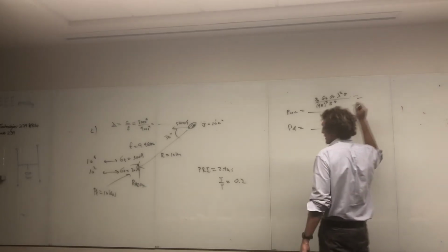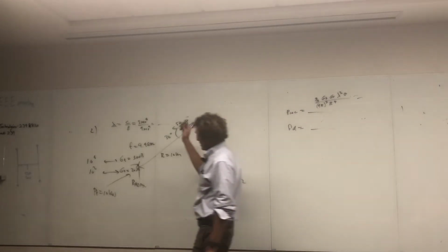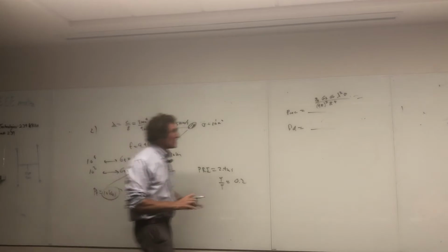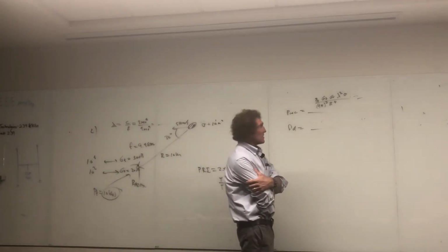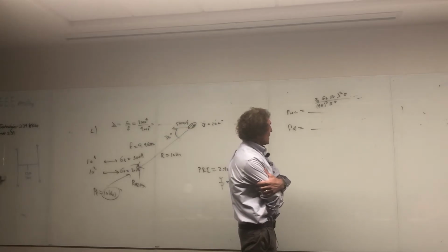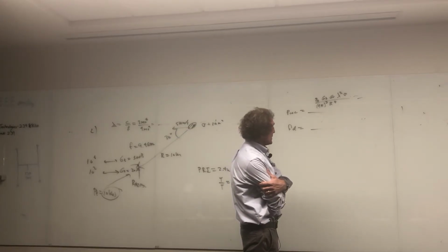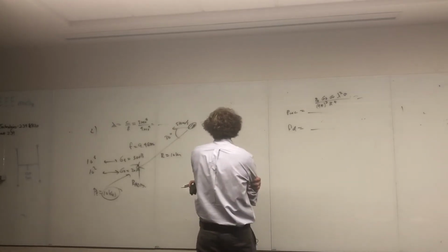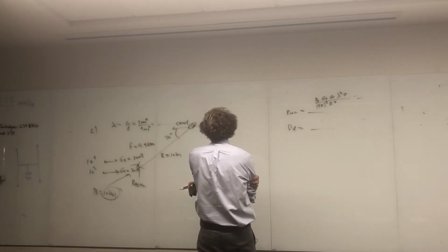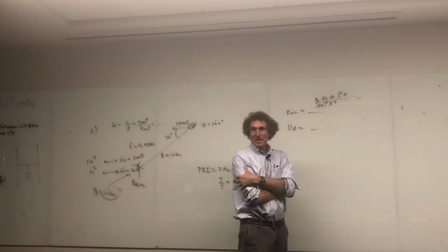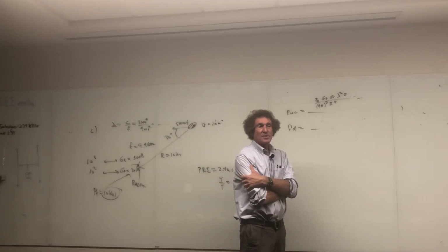Remember, transmitted power right here is 10 to the fourth watts, not 10 watts, 10 to the fourth. Gain of transmitter, 10 to the third. Gain of receiver, 10 squared. Lambda squared sigma over 4 pi, but it's R to the fourth, and R in this one was 10k, so that's R. 10 to the fourth to the fourth is 10 to the 16th, which is a big number. But what do you guys get? Run them again, make sure it's right.